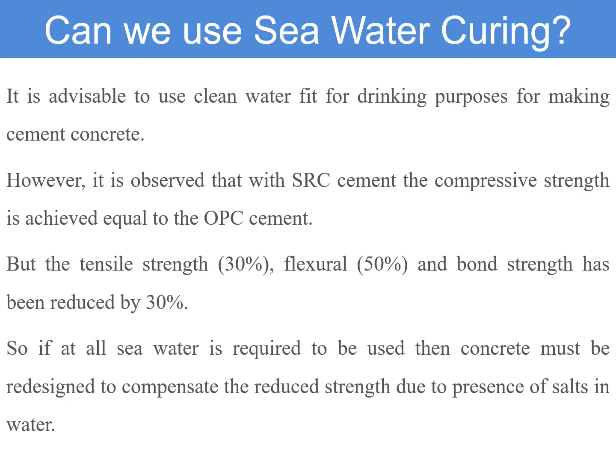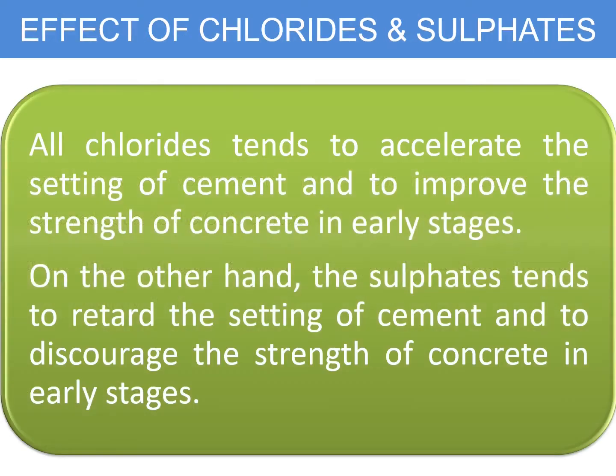be redesigned to compensate for the reduction in the tensile, flexural and bond strength by changing the water cement ratio or other measures, which is basically happening because of the presence of salt in the water.